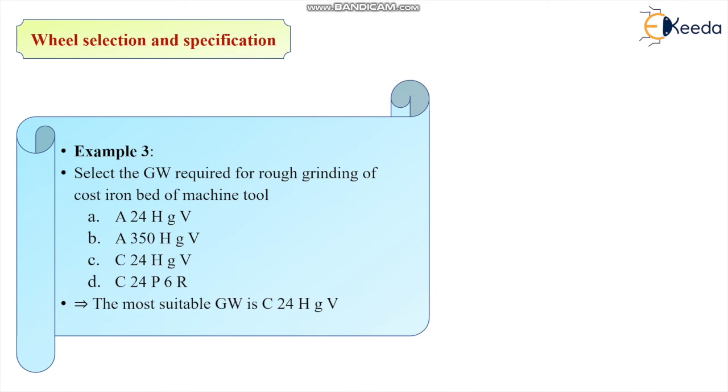See, the most suitable grinding wheel for this operation, you can have C24HGV, and the reason why it is so, you can conclude very nicely if you have gone through these videos.